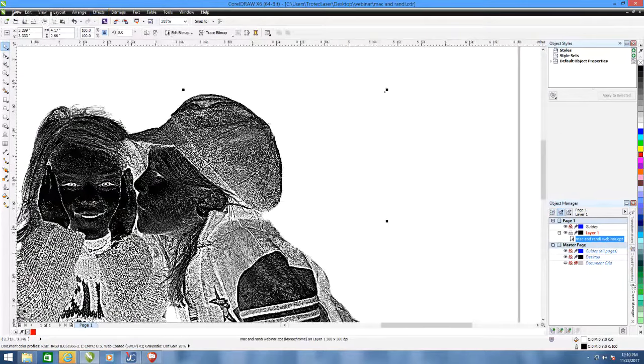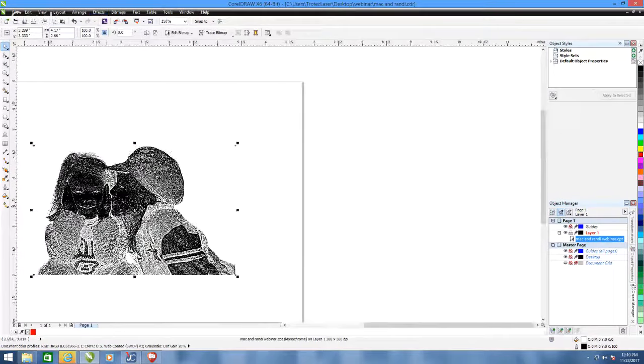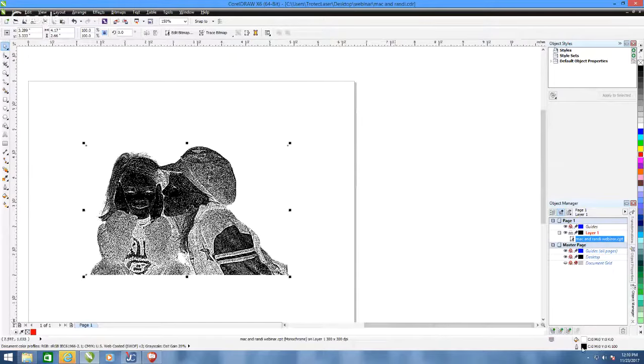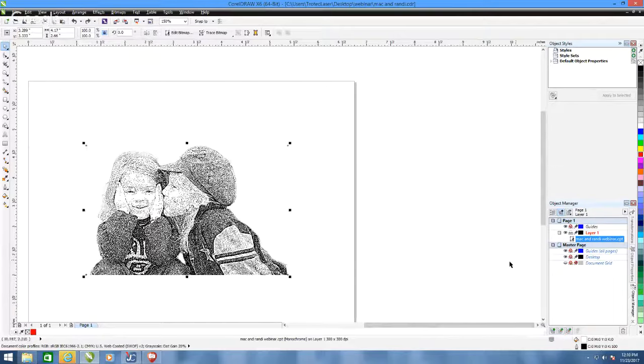Now for you Rayjet users, I believe there's a few of them here, you notice that the colors are actually CMYK, and that would probably be a good thing even if you're using the Speedy machines. What I normally do is right click on the black, and you notice this has now changed to RGB.